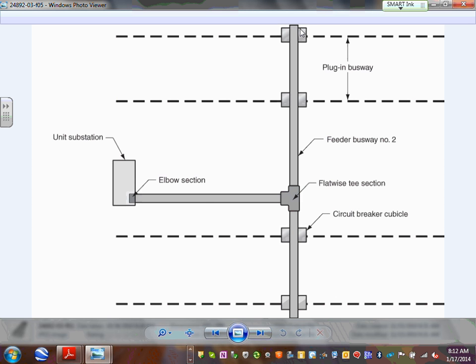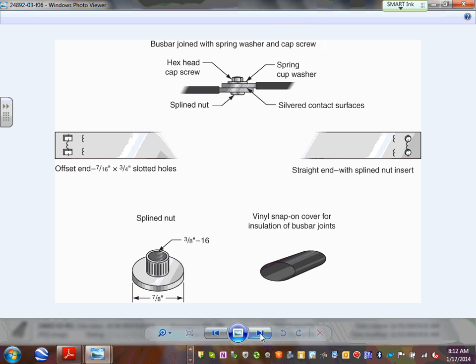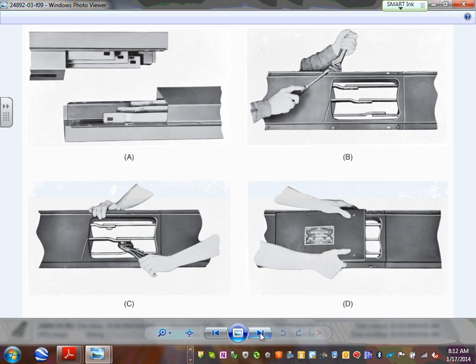Here's how you lay out your feeder. When we looked at this one, guys, you lay out your feeder busway, that dark stuff, and then these hidden lines are your plug-in, and the plug-in busways are tied to the feeder busways through a 225 amp circuit breaker. We talked about this. A lot of hardware, a lot of torque that you have to do. If you're an electrician, Adam, you can see all the tools that you have to use to torque all these connections.